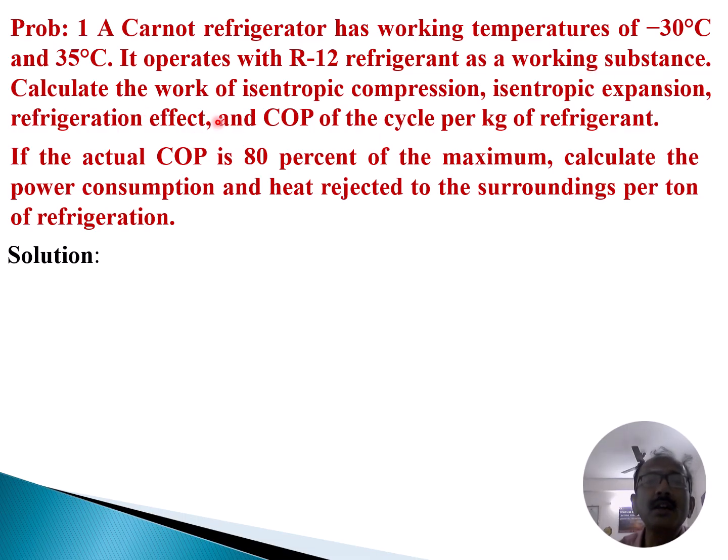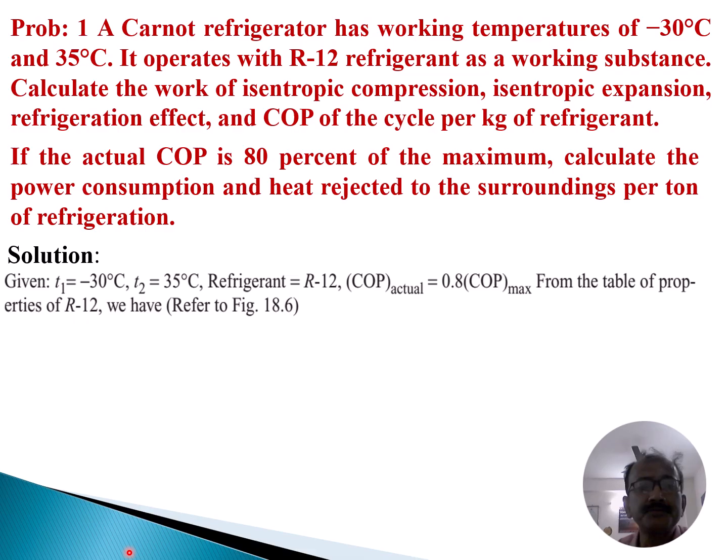Calculate the work of isentropic compression, isentropic expansion, refrigeration effect and COP of the cycle per kg of refrigerant. If the actual COP is 80% of the maximum, also calculate the power consumption and heat rejected to the surroundings per ton of refrigeration. Now we come to the solution.